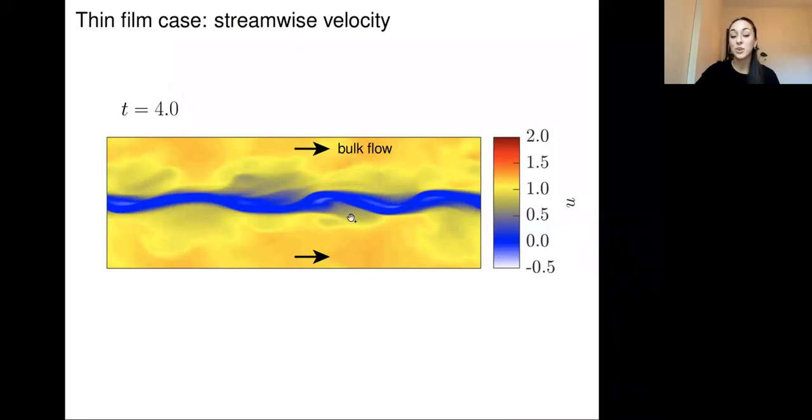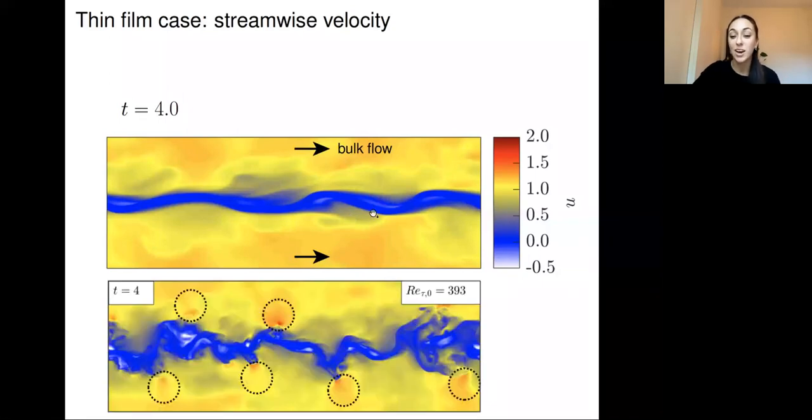And to contrast this very quickly to what it looks like at a higher Reynolds number, and how important it is to get this Reynolds number effect in there, we see that at a higher Reynolds tau, many smaller scales are being introduced to the problem. The sheet is very much more convoluted at this stage. And we also have more regions of flow reversal. And here in little circles, I've highlighted very high speed regions, as I said, over those little tips that were forming, those little lobes that peeled off from the main sheet.